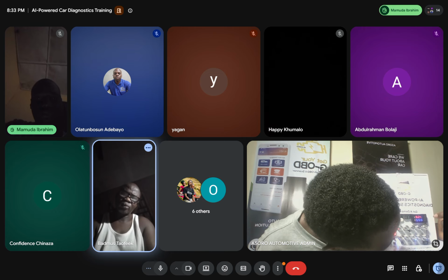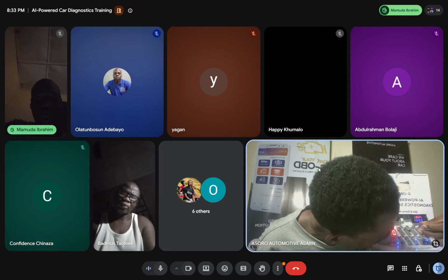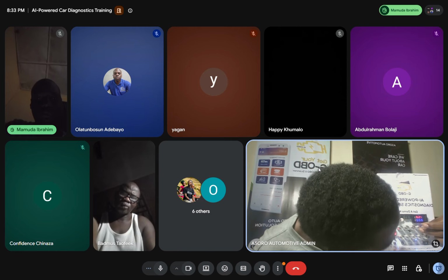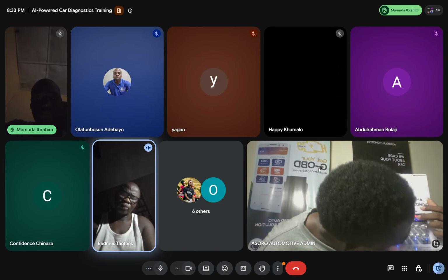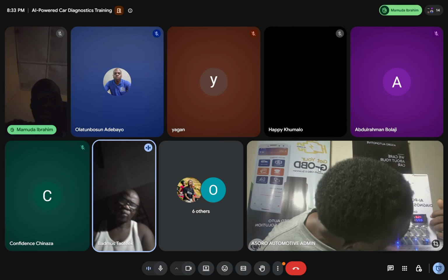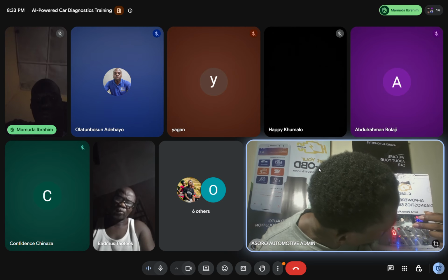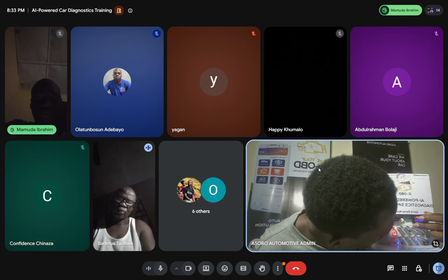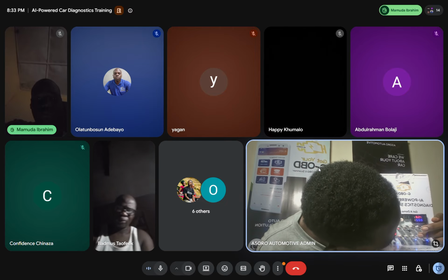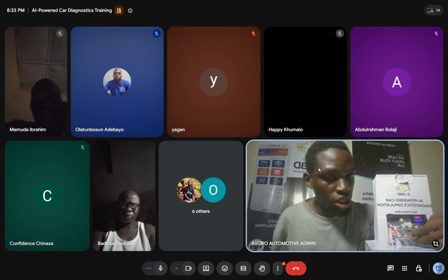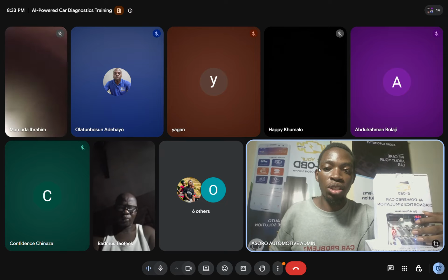We have throttle position, intake manifold pressure, ignition timing advance, calculated load value, fuel level input, vehicle speed, and engine RPM. You can adjust these values, so you can simulate any case that you want.